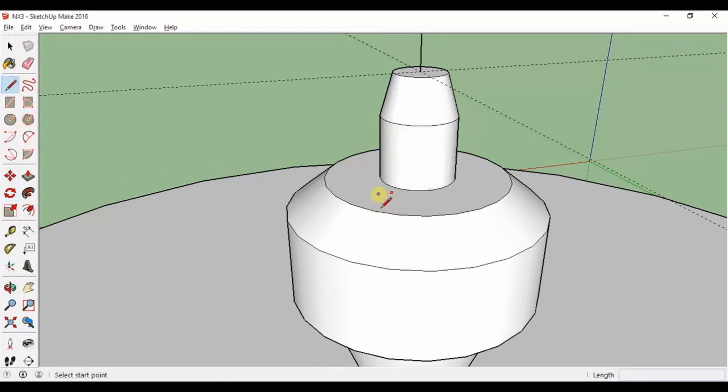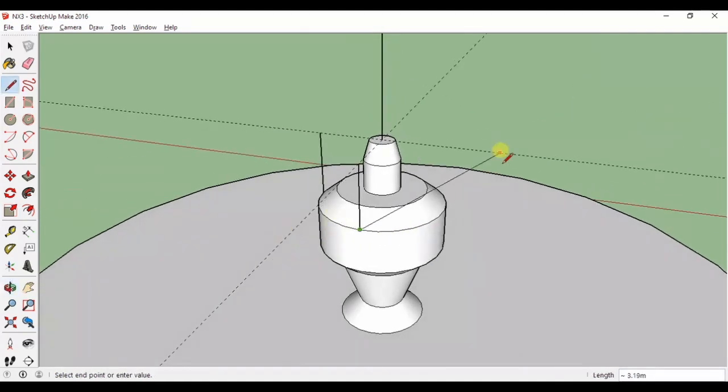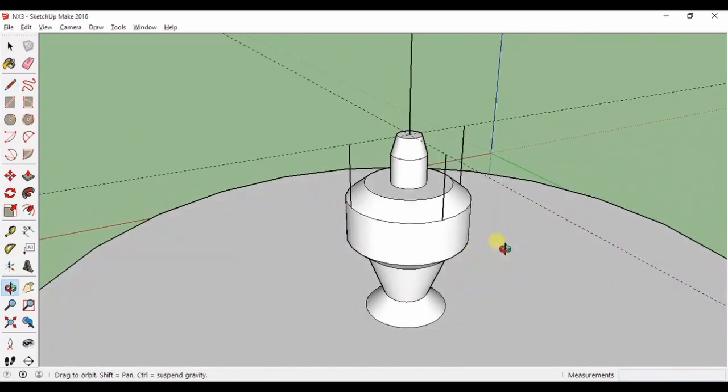One alternative is to slightly cheat by taking the line tool, hovering it over the previous guidelines, hold down the Shift key on your keyboard to attach a zip line, and this gives me a constant line of reference. So once I hover it over roughly where I want to draw, and once it turns blue, I know I've got a vertical line that accurately attaches to the cylinder. This marks out one of the 90-degree points. One click and the zip wire attaches properly to the guideline. Another on the cylinder gives me my reference line.